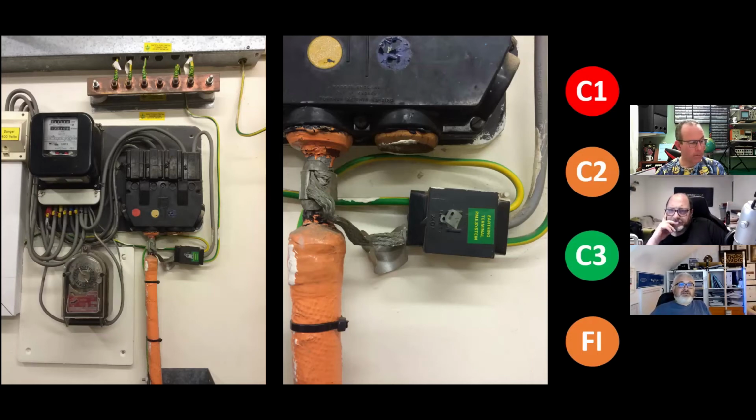Simple as that. Imagine if there is a loose connection in a joint further upstream on that neutral, the old PILC neutral. You're definitely then going to get a potential difference between the sheath and that earth bar. Only because the sheath has two R2 values. So it's the sheath that's the problem. And so you leave them linked, which then drops the overall impedance, which is why there are even statements that state that if a cable is buried, you can consider the old PILC cables as a longitudinal electrode, a horizontal electrode. You're going to have circulating currents, aren't you?